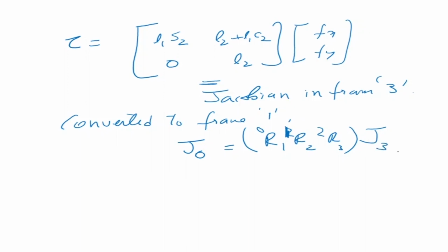So if you do that, we see that the Jacobian relates not only the velocities, it also relates the forces which are acting at the end effector. And now let's look at a very simple kind of proof, where we have a link and we have a force acting. There is some force acting here, and there's a joint torque tau.